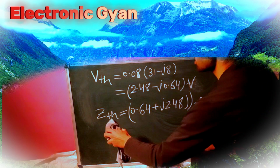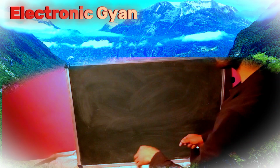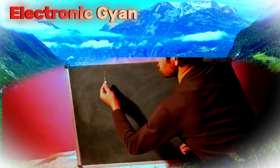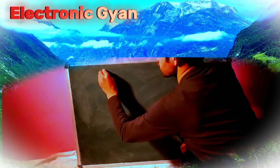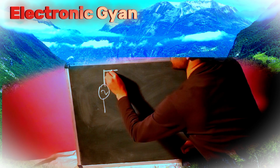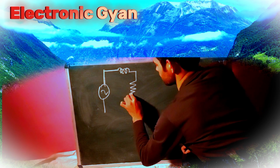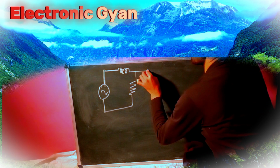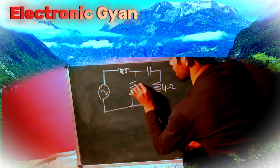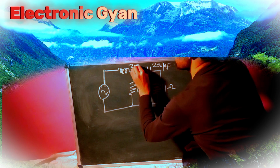Okay, so now we are going to replace that network that we have obtained by this Thevenin equivalent voltage. Okay, so what was the circuit? Our circuit was this one. So this is my inductance, and this is my resistance here, and this is my capacitance, and this is 4 ohm, this is RL, and this is 200 microfarad, and this is 2 millihenry.